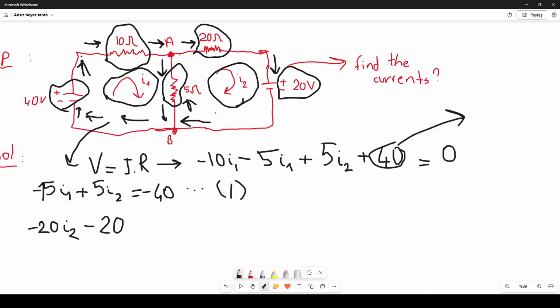And again, I come to the intersection point, but this time 5I2, again 5I2 is in the negative direction because it is the value of this mesh. We have I2 as the current value, but in the reverse direction we have also what? We have also 5I1, right? This is the contribution from the left hand side mesh. So don't forget to add this value. So it is just like taking the difference, right? We don't know which one is bigger, right?